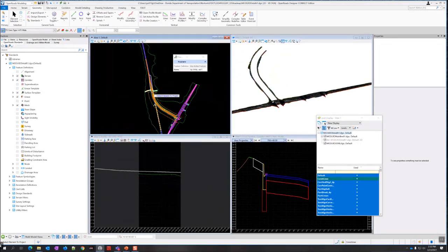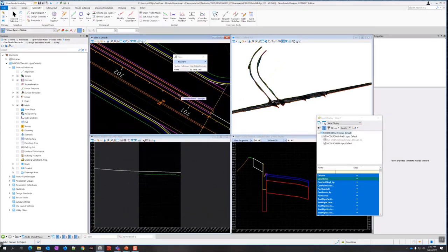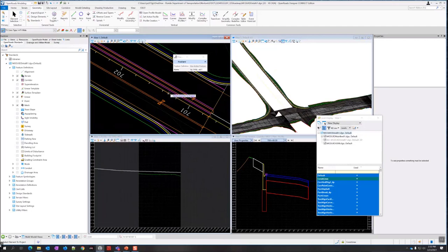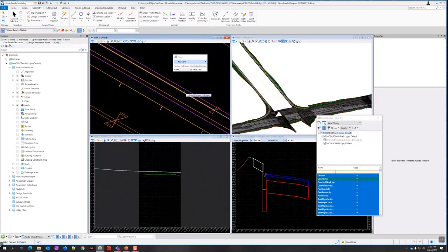So I'll just go into the next one rather than opening a profile model for all of these. Come down here, select the pavement asphalt PM, select the traffic separator one in this file. There's my line. Do the same thing for the other side. Pavement asphalt PM, plane element to project onto, traffic separator. There it is. So there's my construction line.